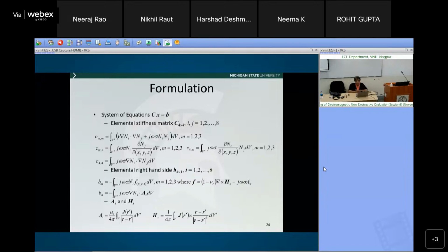Because see, the thing is, in eddy current, in the problem that I'm looking at, suppose you just imagine I'm doing a raster scan, right? If the coil and the geometry were all integrated, at each position of the coil, it's a different finite element problem. I have to mesh the coil, I have to mesh the sample, I have to input the source and then do that. And now I'm decoupling it. If the coil geometry has changed, from a pancake coil to a plus point coil, I have to go back and redo everything.